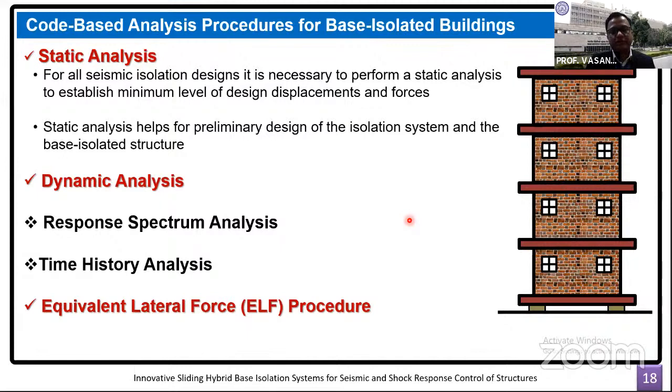Now, in the absence of the codal provisions in India, when we took up this project, we relied on some international codes and saw what practices they have adopted. So there are different procedures available, and this morning, Professor Deb has already explained the design procedures, so I'm not going to repeat those parts. Very quickly, there are static analysis, dynamic analysis, and equivalent lateral force procedure available in the different codes, particularly that from the US, ASCE 7, and that from Japan. Out of that, the equivalent lateral force procedure is pretty simple and straightforward. It is comparable with the seismic coefficient method.